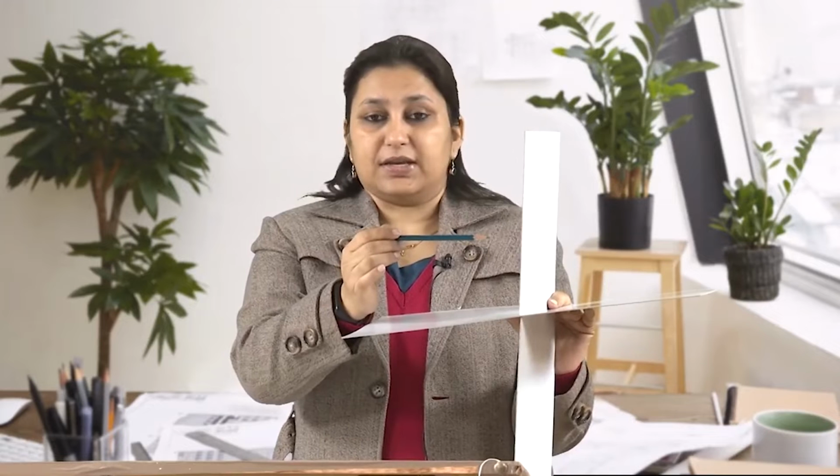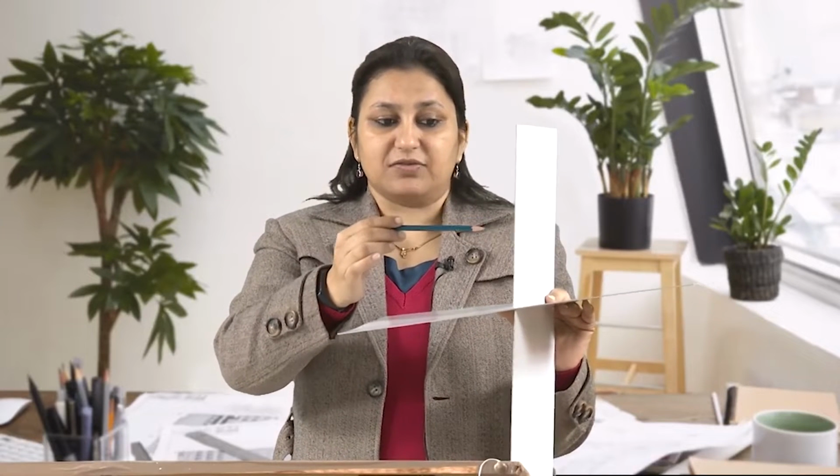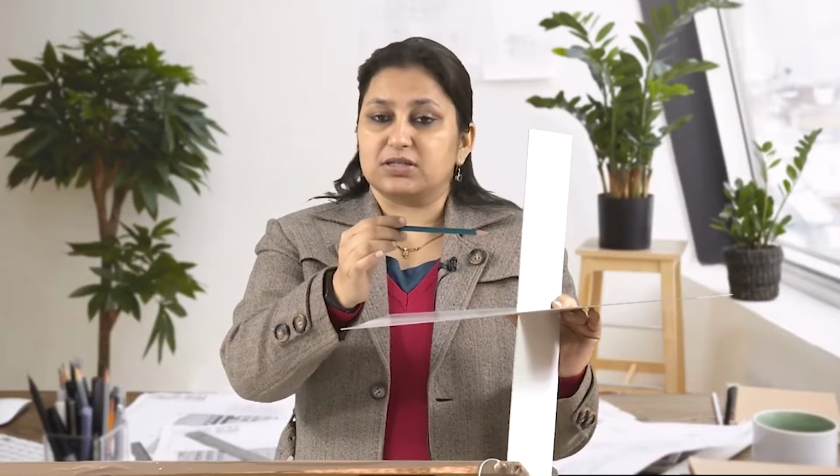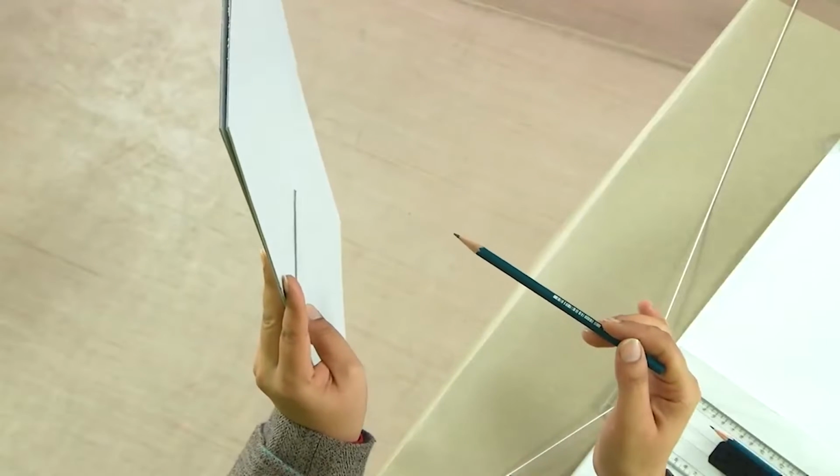So, if you remember, this is how we understood the quadrants: first quadrant, second quadrant, third quadrant and fourth quadrant. Now just imagine that I have this pencil and the tip of this pencil is actually the point which we are considering. Suppose I place this point at some distance from VP, say 5 centimeters from VP and 7 centimeters from HP, which is the horizontal plane. I will start to draw the projections on a flat sheet of paper like this. So let us see how it looks when we draw it on the sheet, and how we draw.